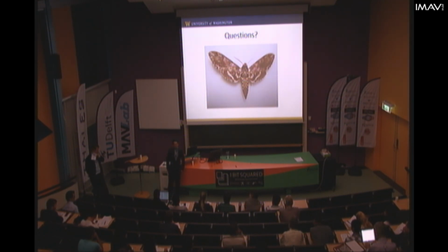The question was, membranes are typically dominated by in-plane stresses, so since we're neglecting in-plane stretching, how accurate is our model? The answer is, although in-plane stretching was neglected, you can actually still get in-plane strains. The reason for that is because of the camber geometry. If you imagine you have two fixed walls and a bent arch between them, if you push down on that, the overall in-plane shape does not extend, yet you still are able to generate these in-plane strains. So we believe that the out-of-plane deformation will be more substantial than the in-plane, but that's the mechanism by which we're able to get in-plane strain without actually considering stretching of the wing. Does that answer your question?